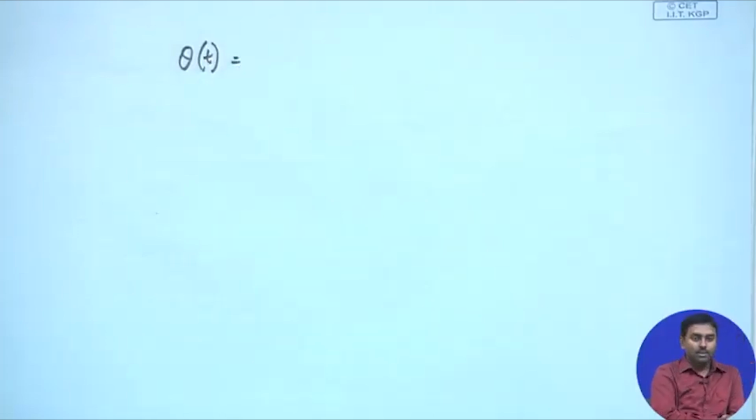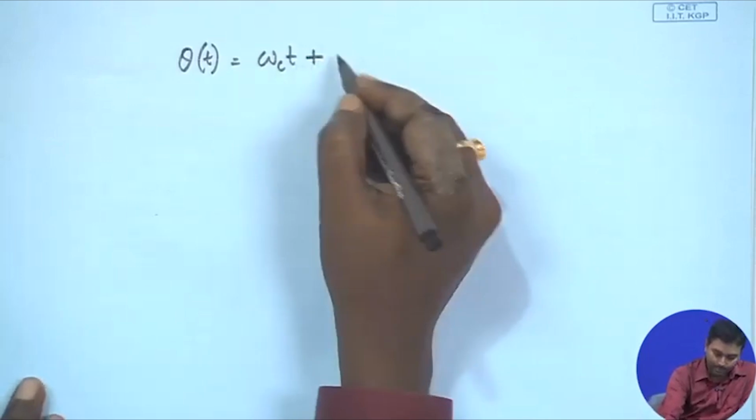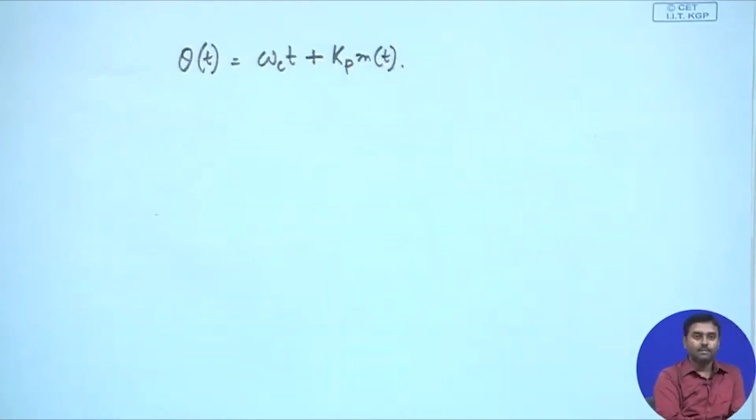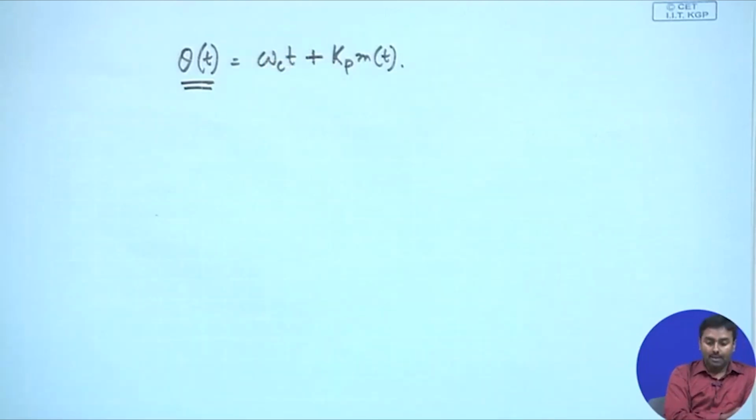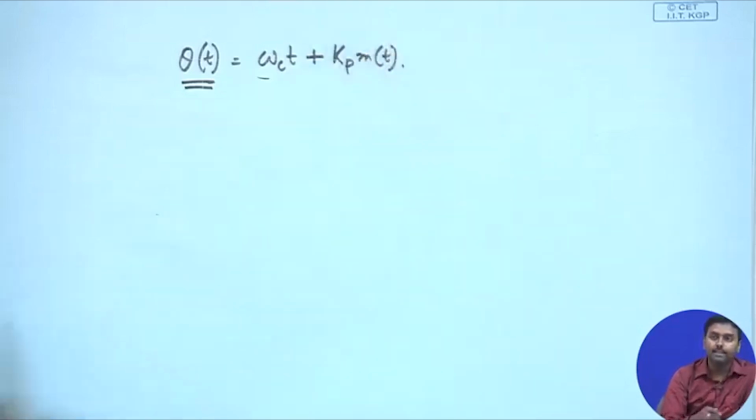So, knowing this relationship, let us see what will happen if I try to modulate a signal, the angular thing we wish to modulate. Let us say I have a theta t. Now, this theta t I want to vary instantaneously with respect to the input message signal, right. So, what I can do is, it must have a constant part omega c t, plus a linear variation with respect to the message, so I can put k p m t. The overall phase being created has a constant part due to the constant angular frequency, plus a variation due to the message signal itself.